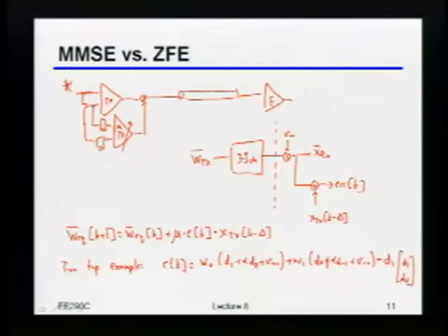But there is actually one type of equalization at the receiver where it turns out that doing this is exactly what you'd like to do. So anybody have any thoughts as to what type of equalizer you would really like to completely kill the ISI? DFE. Yeah, DFE. Right?